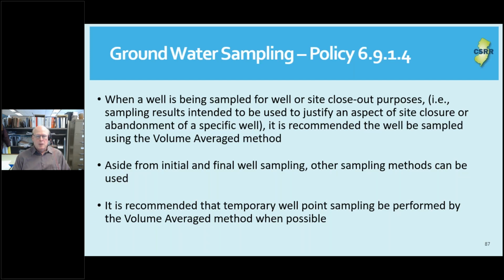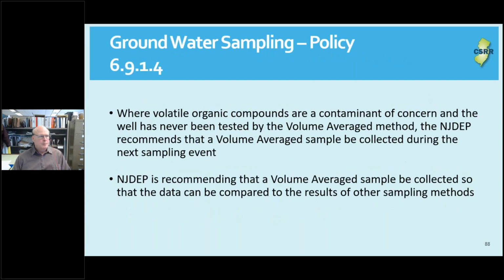Since temporary well points are frequently installed in areas of limited or no pre-existing groundwater data, DEP is recommending that temporary well point sampling be performed by the volume averaged method when possible. Next slide, please.